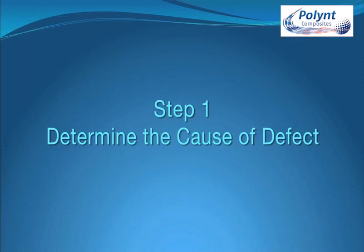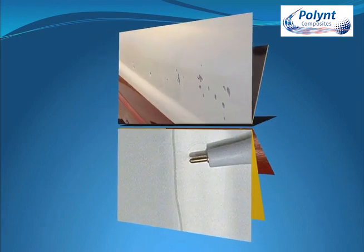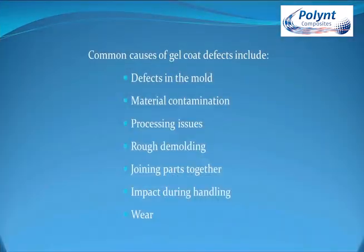Now let's look at this process in more detail. Step 1. Determine the cause of the defect. Also determine the type of the defect and the type and extent of the damage. Common gel coat defects include scratches, chips, blisters, cracks and fibre print through. Understanding the cause of the defect may help you prevent it.